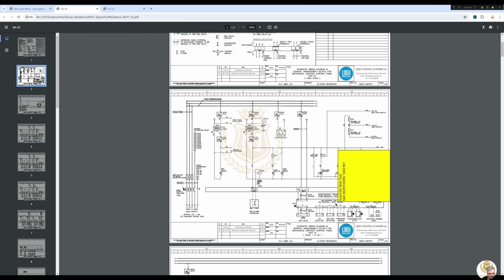Fire alarm, we've got the gas detection system, which has a gas and enables a gas valve, does the CO2 detector, natural gas detector, pressure sensor, plant room, and thermal links across the boilers. Just 3 boilers there. BMS out, energizes relay 137. 137, once it's energized, is healthy. 137 goes across to that.